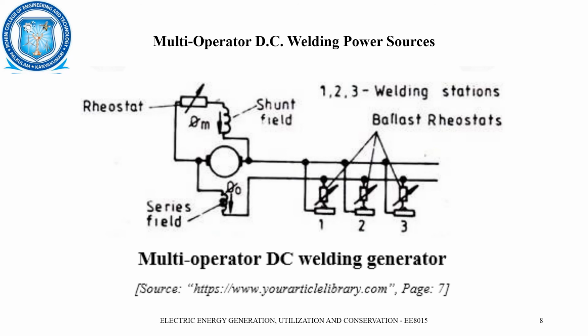In the tapped reactor method, output current is regulated by taps on the reactor. This has a limited number of current settings. In the moving coil method of current control, the relative distance between the primary and the secondary windings is changed. When the coils are more separated, the output current will be less. The current output will be very low. In such cases, we may go for the other methods.